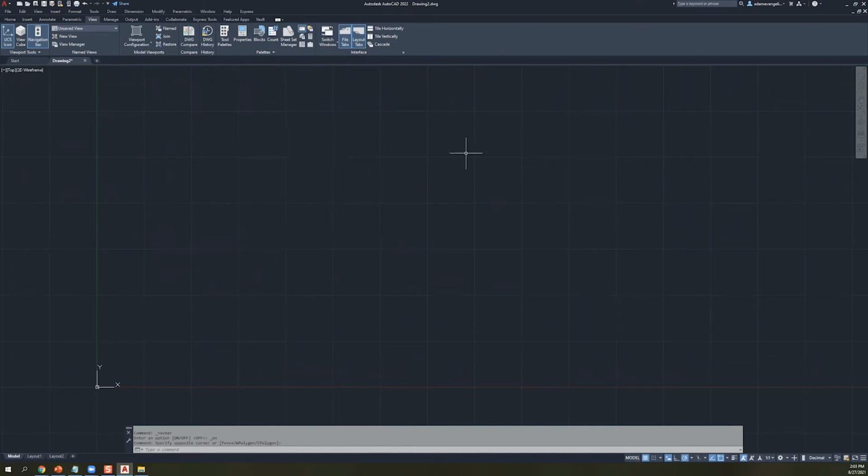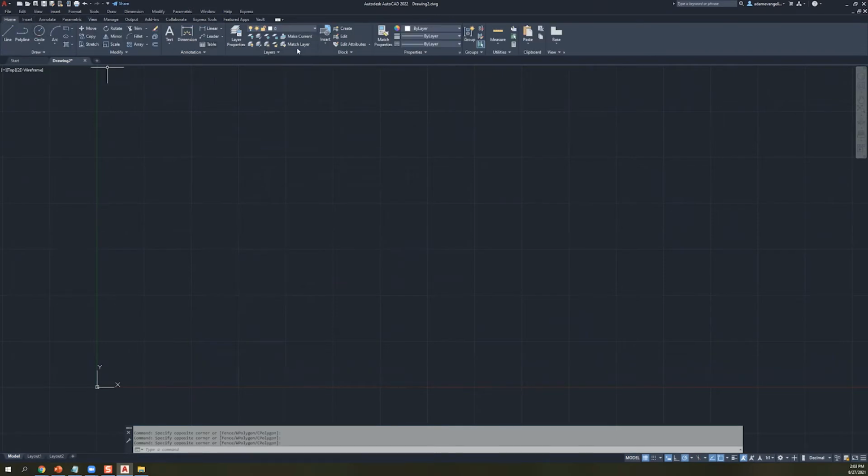You have your cursor, of course, up top, and it's kind of a little crossbar over there. And if you click, you could start a selection window. Nothing to select on screen quite yet, but we could also just see what the other stuff is on screen over here, right? The bulk of AutoCAD happens in these toolbars up top over here, right? So obviously this is the home tab. All the commands and all the functions in AutoCAD are going to be largely organized into these ribbons and panels, right? I'm going to be using probably a variety of different language to describe this stuff, but I call this the home tab, call it the home ribbon, call it the home section, or call it whatever the heck you want.